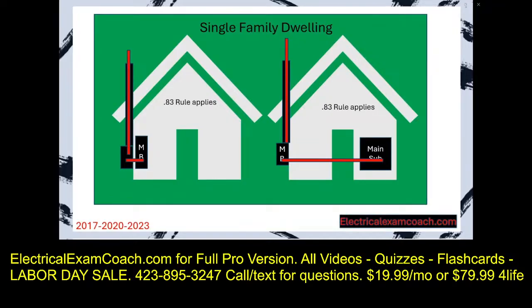Now the rule with this is that it has to be the panel that feeds the entire structure. You're not allowed to use it on other sub-panels or on any sub-panel that does not feed the entire structure. You have to be very careful with that one. So we're allowed to apply it on this one on the left for the whole wire. We go use that table and size our wire based off the table.